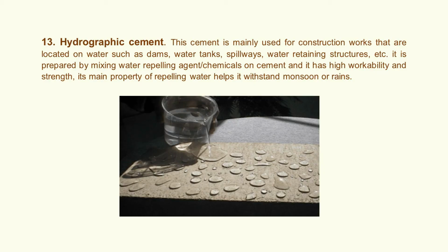This cement is mainly used for construction works that are located on water, such as dams, water tanks, spillways, water retaining structures, etc. It is prepared by mixing water repelling agent or chemicals on cement, and it has high workability and strength.